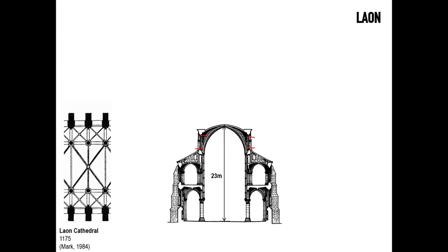This is a Gothic building, but that allows some light from the top. In due course, you'll find that this building has been altered to also introduce some semi-quadrant buttresses, but this would have been the original configuration. The building has a sexpartite vault, so you have two diagonal ribs and an additional transversal rib also at midspan.